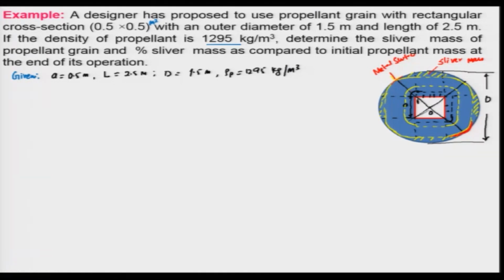We will take this as a point here. Let us say this is your A, and if I consider this point as x, I will have to find out how much maximum web thickness we are having. That means this web thickness can be from A to O. The web thickness is delta, and this is also your delta. So this delta will be basically equal to O x minus O A, that is d by 2 minus O A.